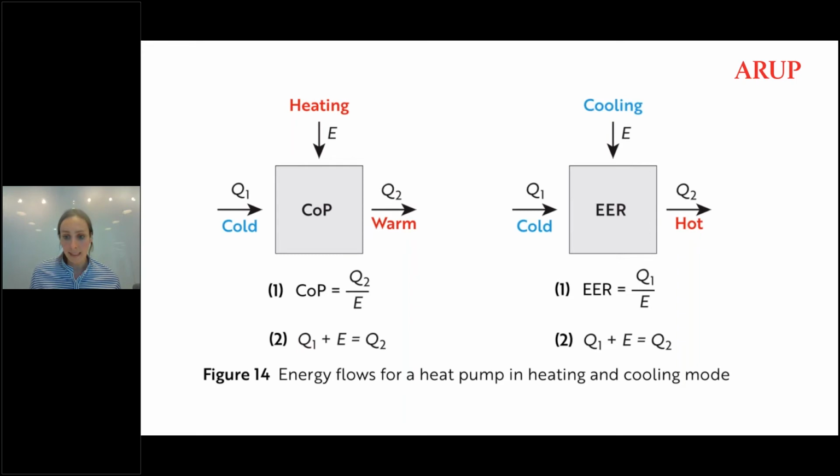These might be completely different for your application in your building, which might have a different climate, a different profile, and different distribution temperatures. So the values shown on data sheets in this instance might be much less accurate than a seasonal energy efficiency ratio that you've calculated yourself using COPs for different source temperatures that you know for your distribution temperatures and weighting them according to your load profile.